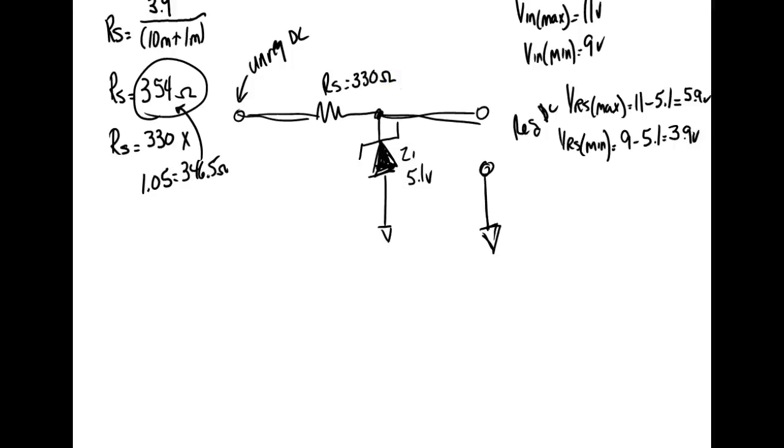What wattage rating do we need on this? We'll calculate that later. So remember, resistors, you have two things. When I say two things, some people say the tolerance, but every device has a tolerance on it, right? You understand that? So we're looking for the unique things that make up a resistor. When I buy a resistor, you're going to have to specify three things. You're going to have to specify the ohms, the watts, and of course the tolerance. But when I say the two things, these are the two things I'm interested in.